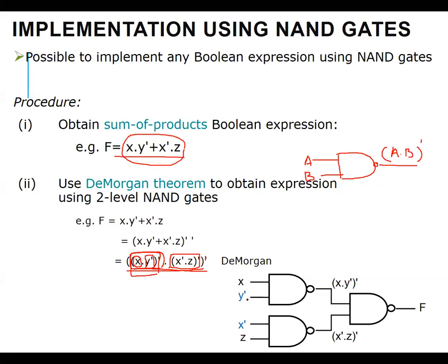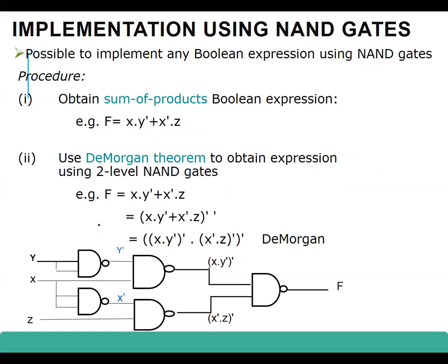So here also this is not represented only by NAND gates because these inputs also need to be expanded. Okay, so here you can see Y's complement is taken by having a single NAND gate and inputting Y into both inputs.